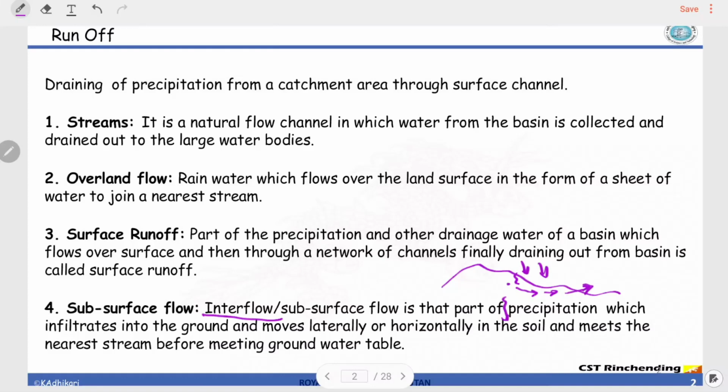It was a landslide area, where a portion of the land had already been washed out as a landslide, and from that portion the interflow is clearly visible. This will eventually come out at some point downstream, flow down again, and finally get into the stream. So that is what we call the subsurface flow or the interflow. Usually in our analysis, the quantity of interflow is so small that we tend to ignore it.